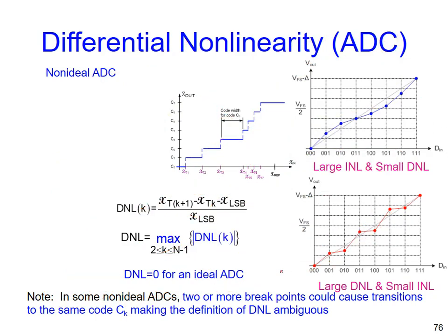Okay? If you don't do anything, according to systematic mismatch, if I'm positive, usually all my neighbors are positive. Okay? According to systematic mismatch. And this is the reason why we need to have very good circuit design or layout to randomize your neighbors.